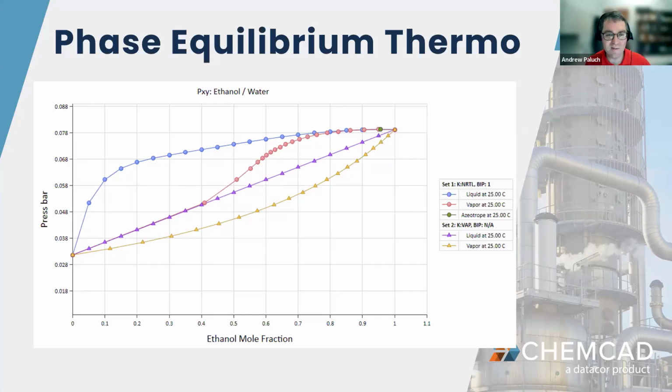We could talk about these deviations relative to that perfect straight line, which is my bubble line, in terms of deviations from Raoult's law and what that physically means. And then also just connecting it back to, well, in our mass and energy balance course we solved everything using Raoult's law, we shouldn't do that in reality, because that's going to have some large effects.